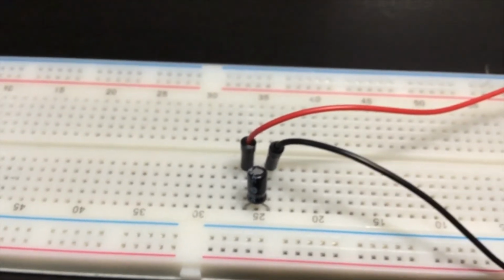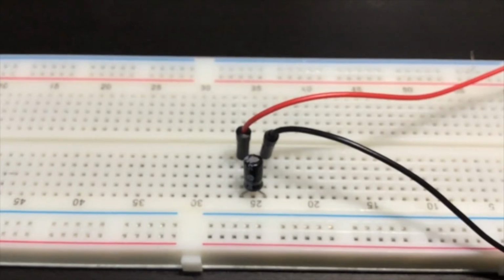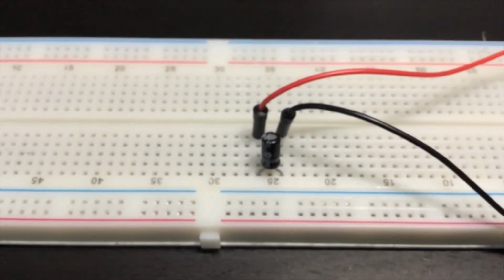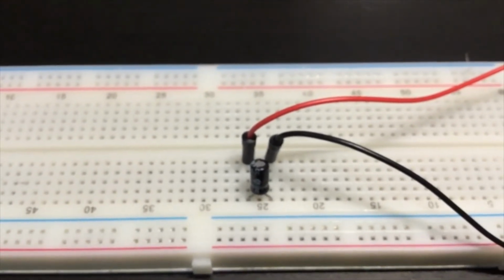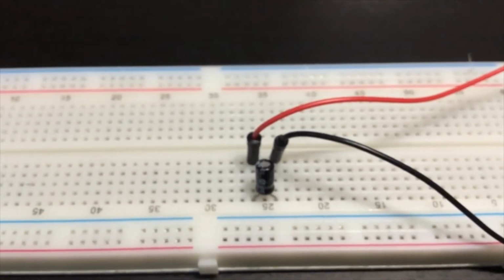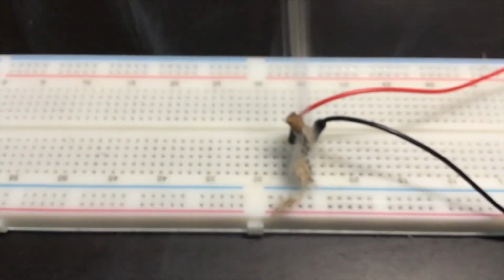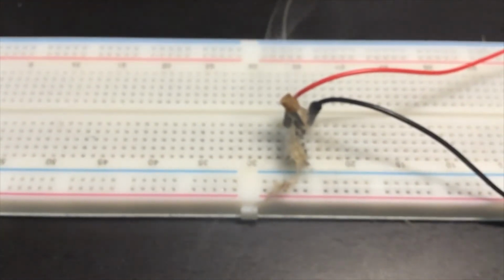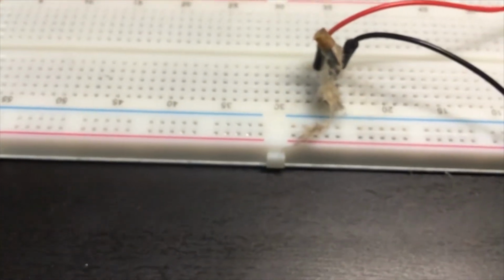Here's a few examples of what happens when you reverse bias an electrolytic capacitor. You're going to like this. Everybody loves this part. And everybody who's ever worked in the lab in an electronics class has experienced this before. Wait for it. Wait for it. There we go. There's the magic smoke you've been waiting for. Doesn't smell too good either. It's even more embarrassing when you end up with those little flecks of wax paper stuck all over your face.